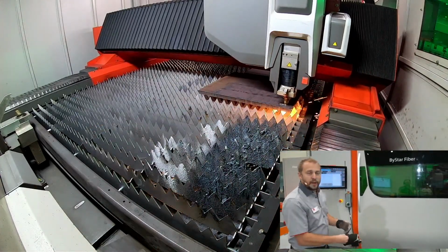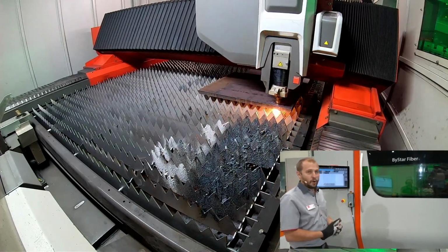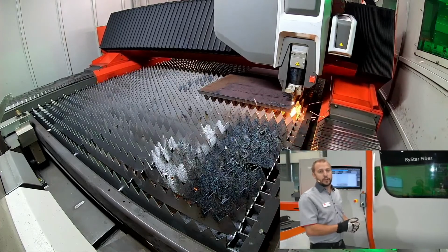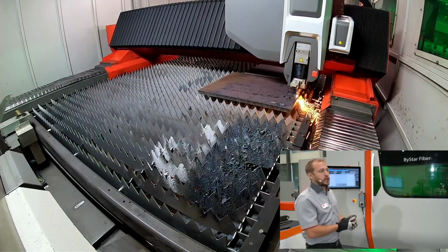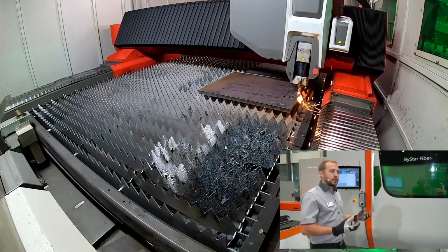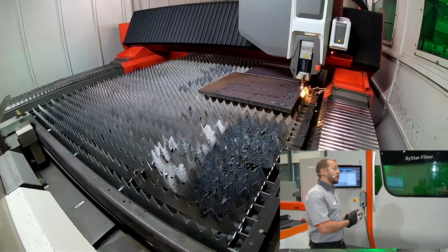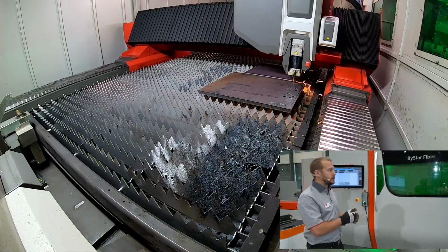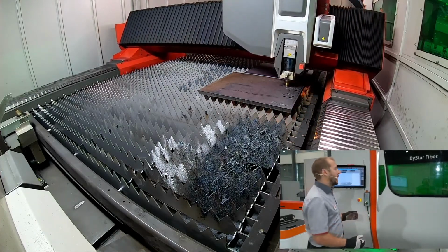So you see I'm wearing my gloves. It means the part is getting warm, of course, but it's getting much less warm with mixed gas than with oxygen, which means we have no heat issue. With oxygen cutting, as soon as we have too much heat, we will have a problem cutting. With the mixed gas, we avoid that problem. So it means we could cut a lot of small parts with a lot of small contours, small holes, a full sheet without any single trouble.